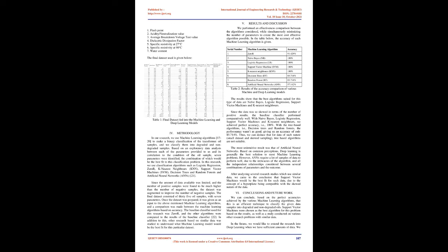With regular DGA test, several problems such as overheating, loose connections, breakdown in cellulose, corona, arcing, and partial discharge can be detected several months in advance, thereby greatly improving the life of the transformer. The most important gases detected during DGA test are hydrogen, methane, ethane, and ethylene.